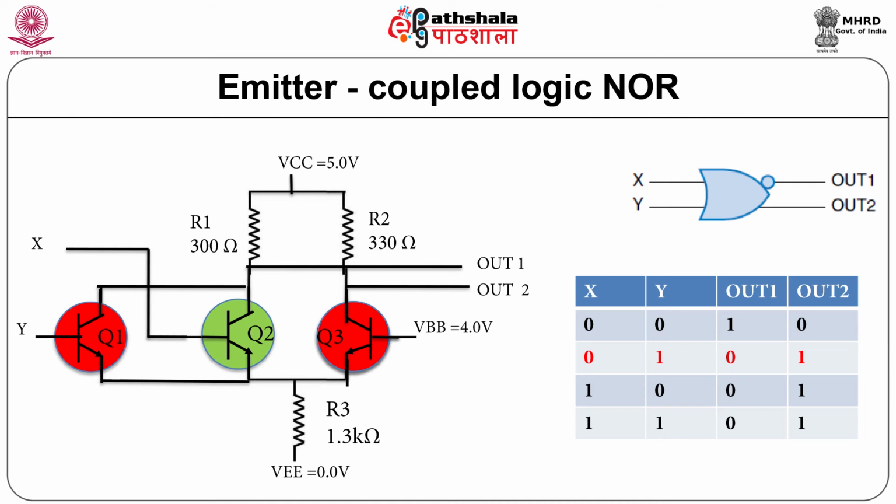We consider the input levels for the inverter or buffer as 3.6 and 4.4 volt, while the output levels that it produces are 4.2 and 5 volt. This is obviously a problem. We could put a diode in series with each output to lower it by 0.6 volt to match the input levels. But that still leaves another problem.